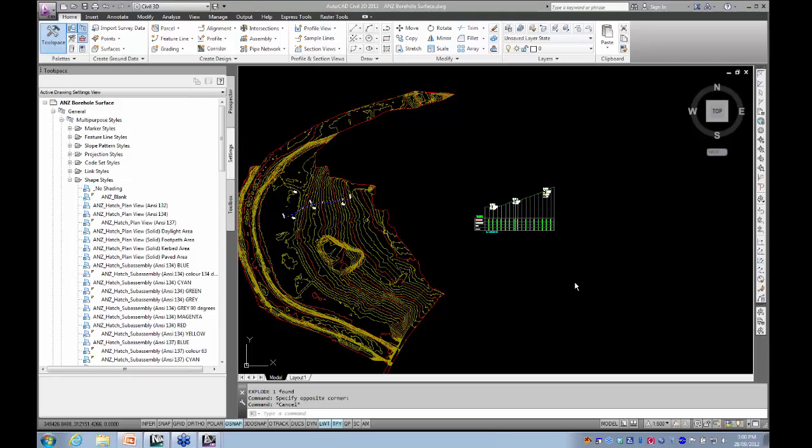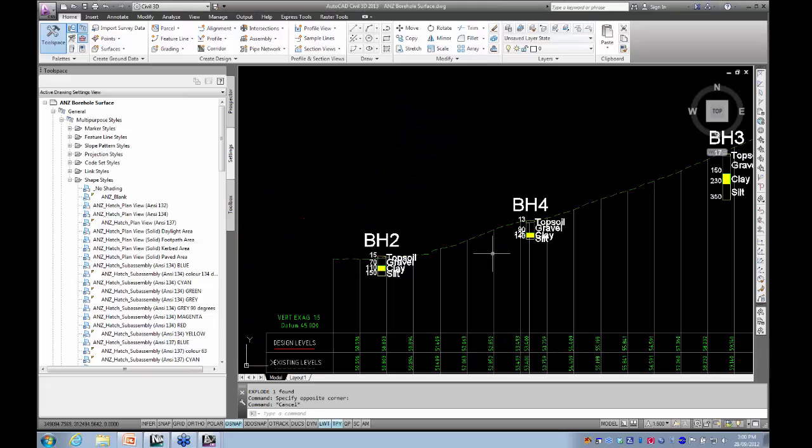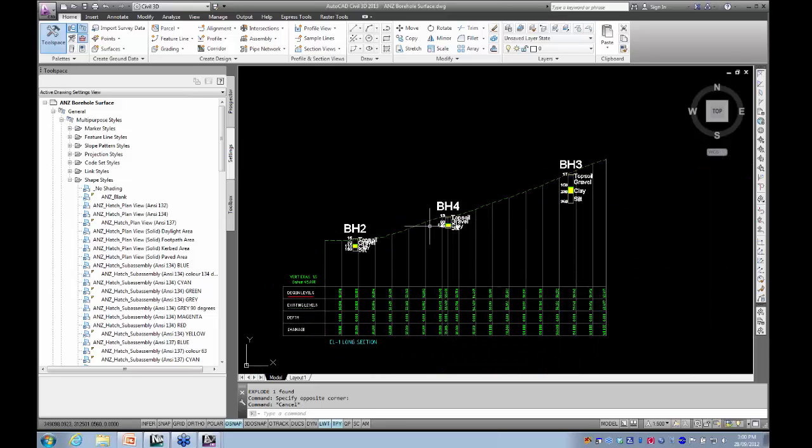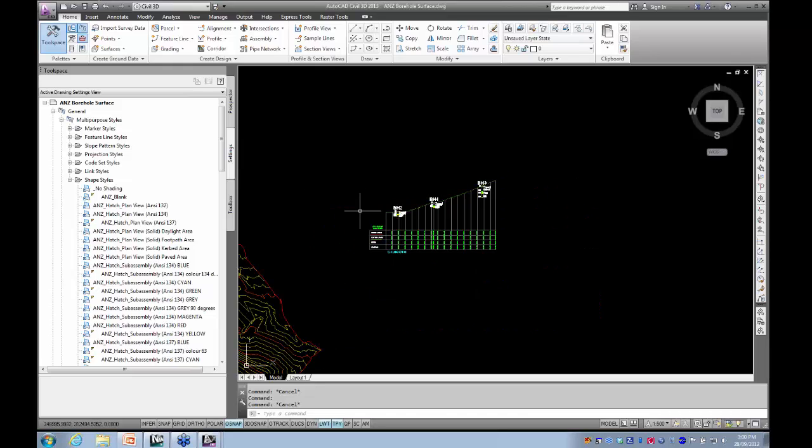If you change the profile view vertical scale on this thing here, it's actually attaching these things to the surface. So wherever the surface is, they'll stay where they're put. If you change it after you've put them in here, you would need to either run the tool again or drag them down vertically. They're non-dynamic, as I said. They are just simply AutoCAD entities, and it's done that way so that you can use these things in AutoCAD without any problems. Translate it back to AutoCAD if need be.